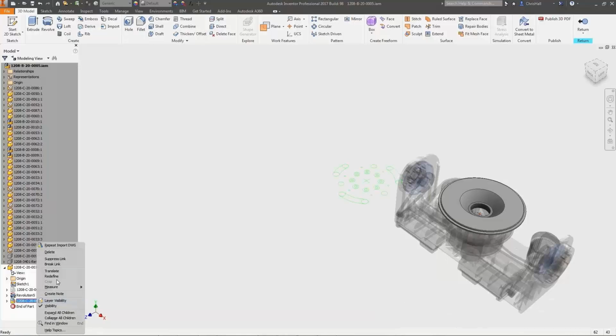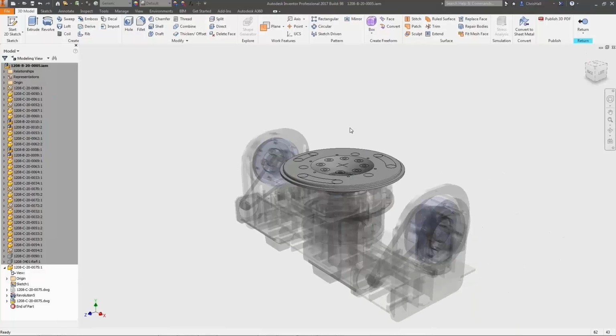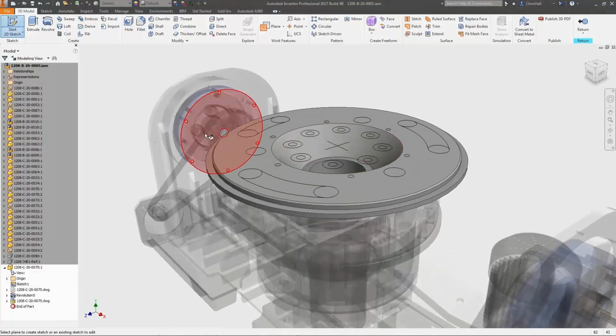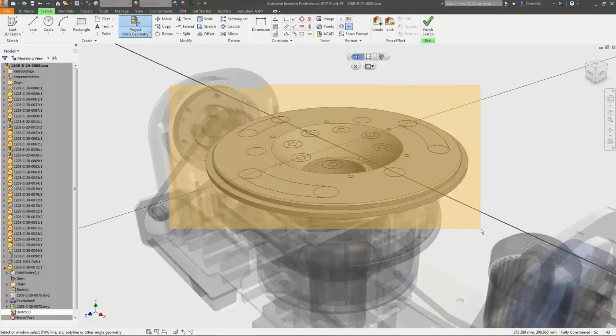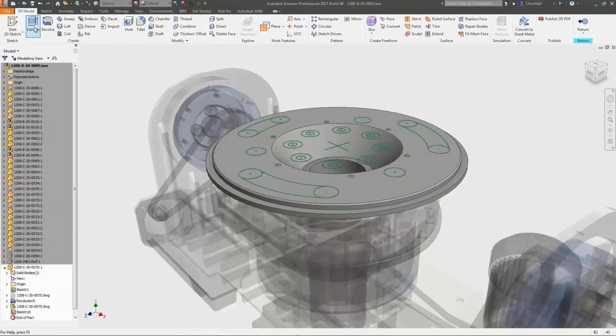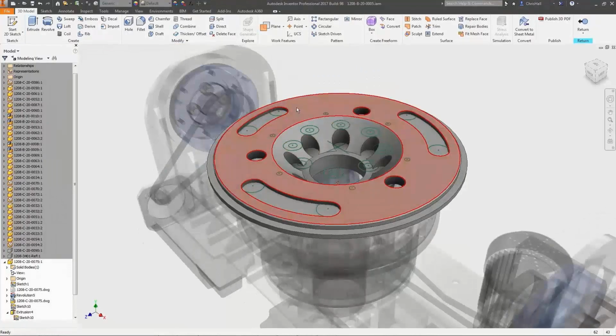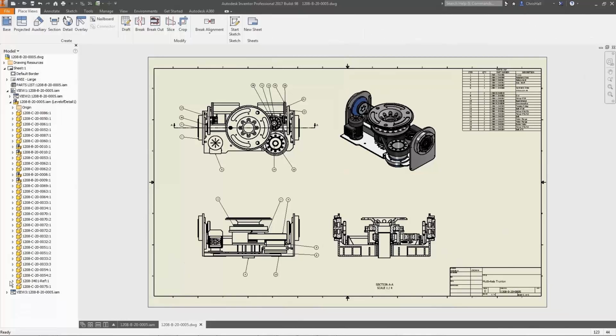So we can use layers to hide any geometry that we don't want, but we can also crop any unnecessary information, improving the performance of this process. Placement of that sketch means that if we're moving and rotating the geometry into position, then that will be remembered. And we can then leverage that to create features and functionality in our design.